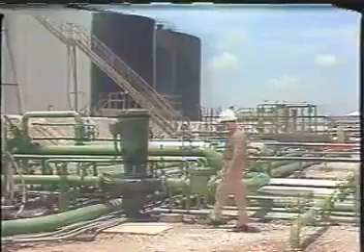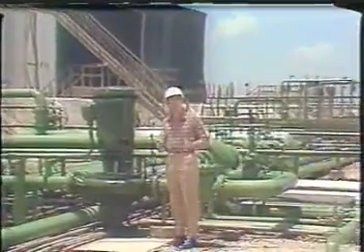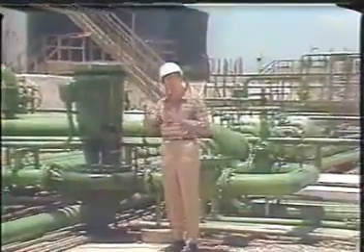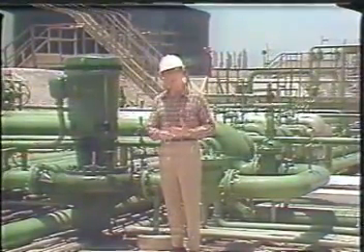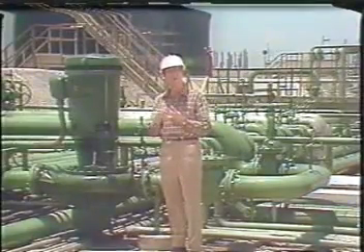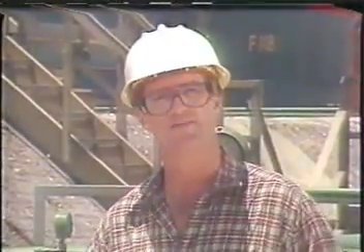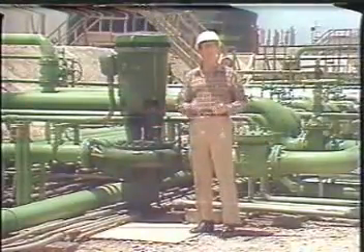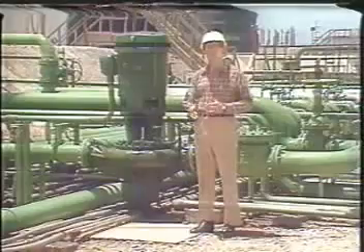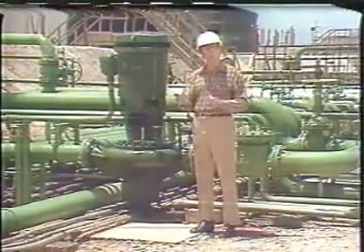Up to this point, we've defined a pump as a mechanical device that adds energy to a liquid in order to move it from one place to another. We've also pointed out that a pump has to be viewed as a portion of a system consisting of a supply, suction, pump and driver, and discharge. In this segment, we'll see why this approach is needed. In the pumping system, the driver is used to convert electrical or heat energy into mechanical energy. This mechanical energy is then converted by the pump into hydraulic energy to move the liquid.